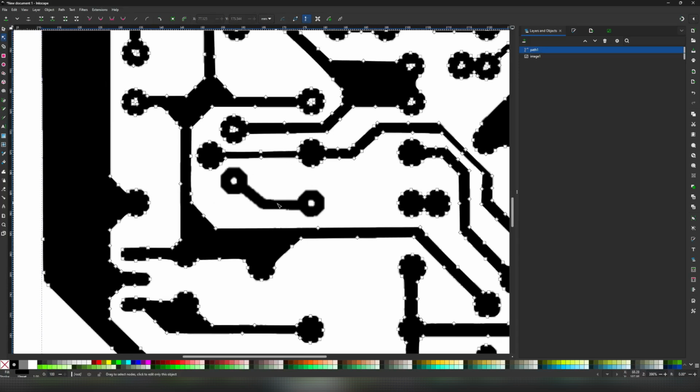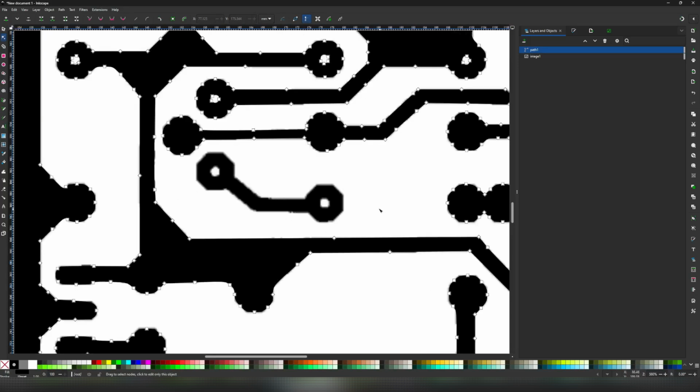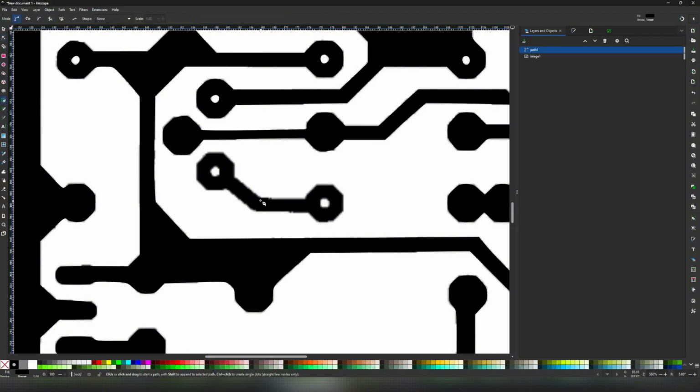So let's say there is a piece of the trace that you're not happy with. You can just delete it. And then the way to move forward is to use the pen tool here, and then you can start tracing the shape yourself. If you just click, you will have non-continuous edges. If you click and drag, you can have node handles, and this one is continuous. The derivative is continuous. So let's go around and trace these.